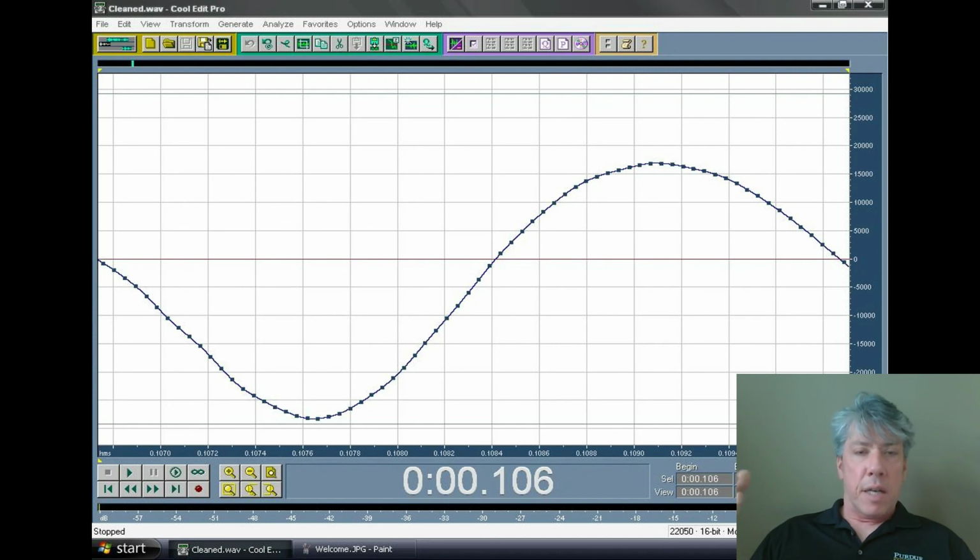And that's about the upper limit of any human being's range, and so there's no point in recording anything after that that an instrument produces, because human beings couldn't hear it anyway, and the purpose of music is for human beings to hear it. So the 22,050 just means how many of these voltage measurements are being taken per time. That's quite a few, right? 22,050 samples every second to represent the music.